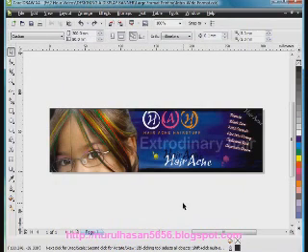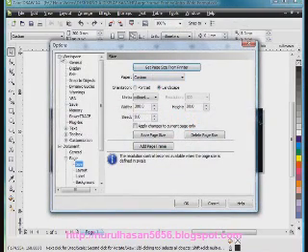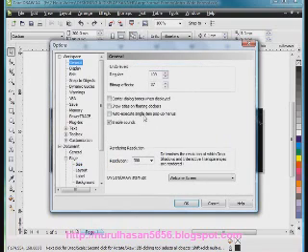The last thing that you would want to be sure that you did is, again, up to Tools and Options, and under the Workspace General option, down the bottom here, the Rendering Resolution. I would want to lower this back to the DPI that my sign writer will print this out at. A 3-meter banner is probably going to be looked at from some 30 feet or quite a distance away, basically 10 meters or more.